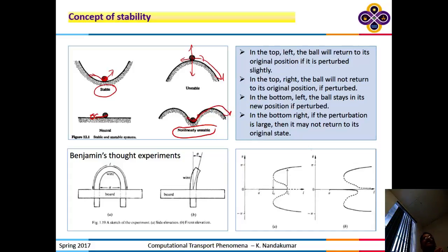This is the idea of linear stability, meaning small perturbations: if it stays stable, you call it a linearly stable system. But you still don't know what happens to the nonlinear response if you give it a large perturbation. And turbulence is about that, large perturbations in the flow. How do they grow? How do they feed on each other? Linear stability is about the onset of transition from one state to another state. That is from a one-dimensional Taylor-Couette flow to a two-dimensional Taylor-Couette flow to a three-dimensional Taylor-Couette flow. Those occur through small perturbations in the experiment that can trigger it to flip.